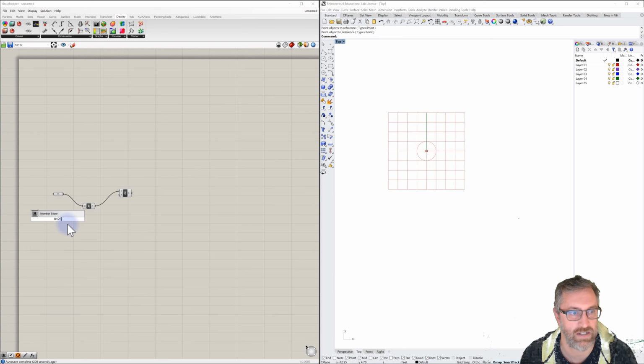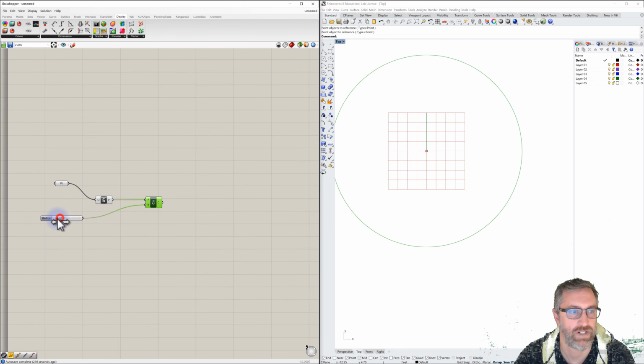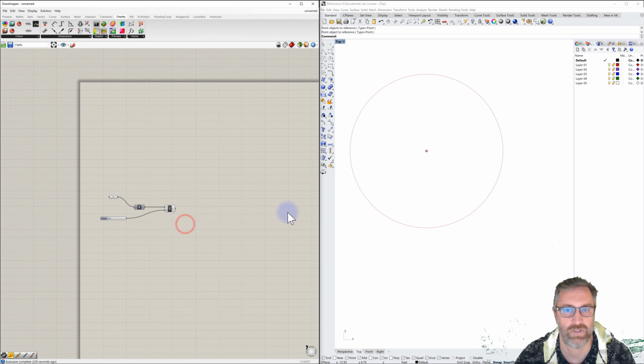And so if I do 8 less than 25 and then equals, it'll give me a slider that's, its initial condition is at 8, and it'll go up to 25. So we'll set this to be the radius. Maybe I can turn that down back to 8. And the reason why I wanted to create my own plane as well is that I can hide that plane now. So we can keep these things kind of simple as we go.